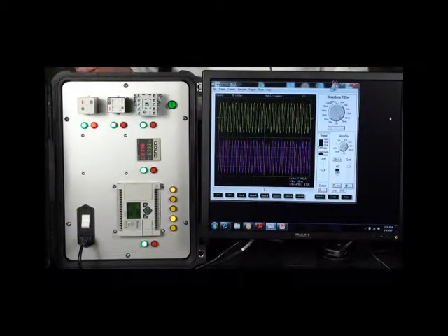This is probably the most common relay today on emergency stop circuits in most factories. Of course, if that relay drops out, the line's going to stop. And people are going to wonder, how did that happen? How can they get it going? And unlikely that they'll actually attribute that to any kind of a voltage sag event.